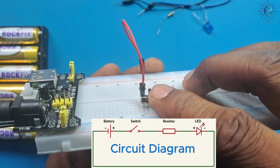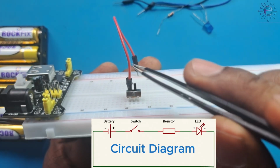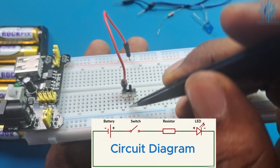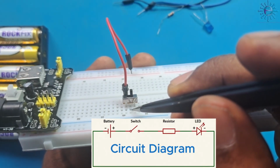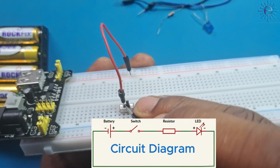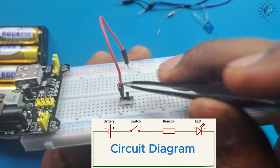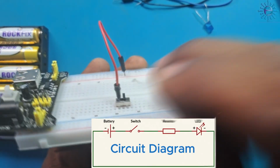You can see that one leg of the switch is connected to where this jumper wire is connected. And you can see that we can connect something else here. Whatever we connect here will be connected to the middle leg of the switch, which we are going to do in a moment. So I will push down this switch. Okay. Remember that one leg of this switch, which is the extreme leg on the left, is connected to this jumper wire. Now, I will connect my resistor to the middle leg of the switch, which is here.